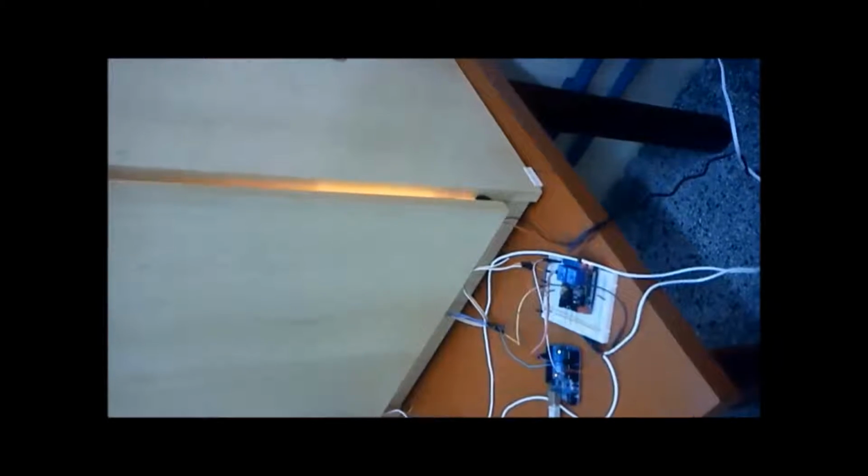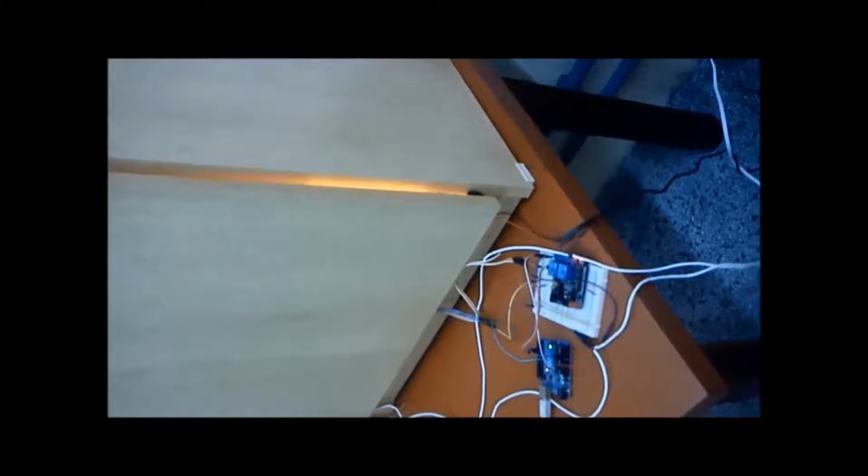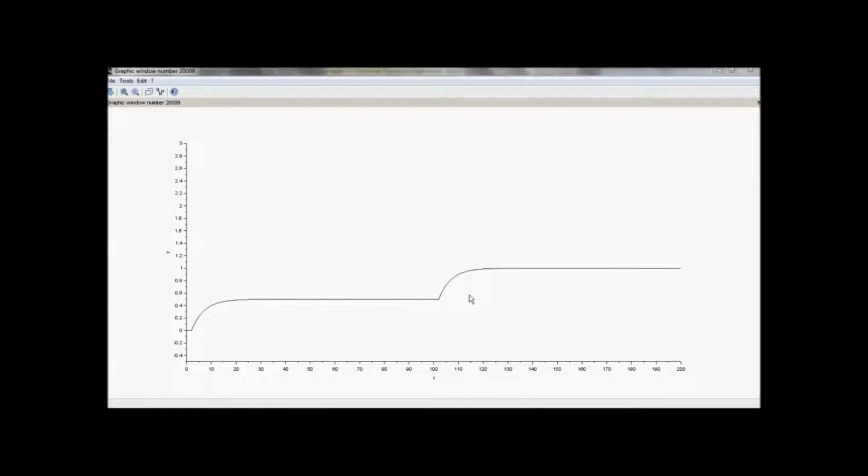In the beginning, by means of pulse width modulation, the applied power was 40 watts, then we wait for the system to reach the steady state, and then the power was changed to 48 watts, what's called the step. After the step, we wait for the new steady state, and with the collected data, we can proceed to the calculation